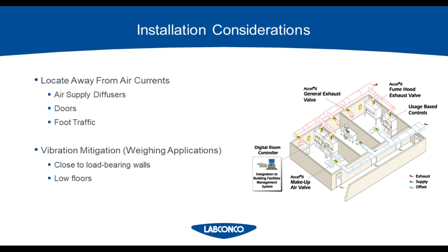Another consideration you should take into account is placement of that hood. This is good practice for any type of hood, whether it's a fume hood, a biosafety cabinet, or a nano containment hood. But you really want to locate this open hood away from any kind of source that's generating airflow. So heavy foot traffic areas, doors that open and close during working hours, or even the supply diffusers in the ceiling for air return.